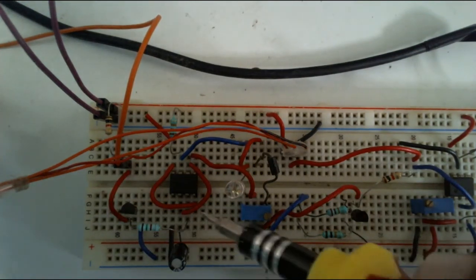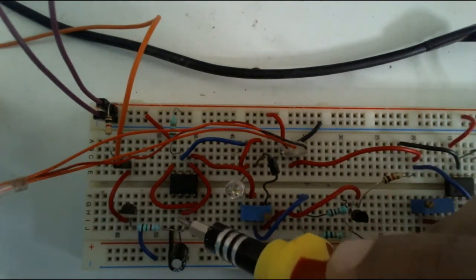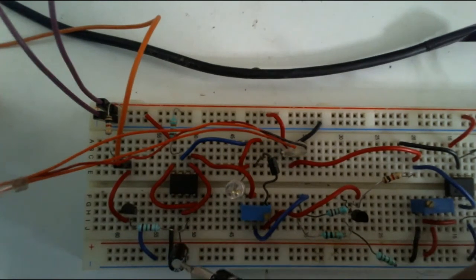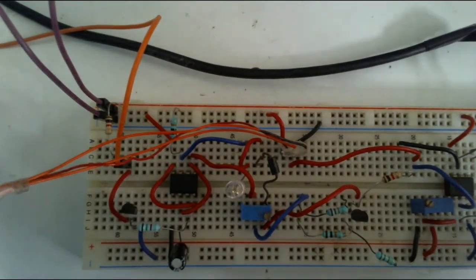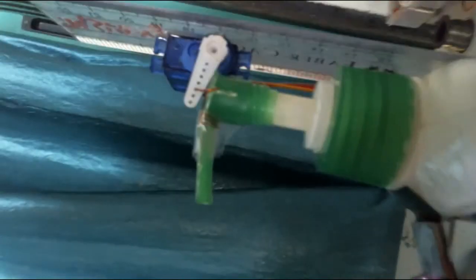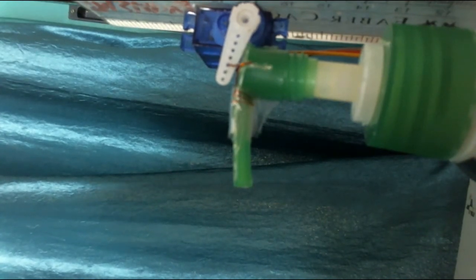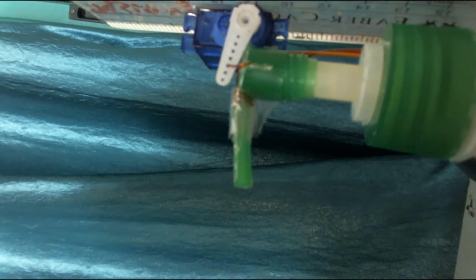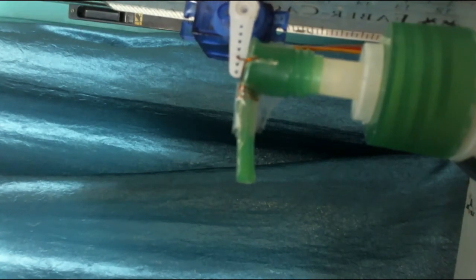So this is the PWM circuit made. This is the output transistor which inverts our third pin output from this 555. This is a 1 microfarad capacitor. This is a 10k resistor. And now I will show you the demonstration. This is actually a project which I have made. I have used a servo motor to pump liquid soap to make an automatic soap dispenser. I will rotate the potentiometer and you will see that the motor moves up and down. Now I will rotate it, and you can see that the motor starts to push against the pump.